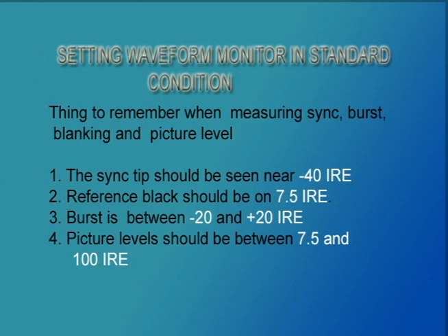The sync tip should be seen near -40 IRE. Reference black should be on 7.5 IRE. Burst is between -20 and +20 IRE. And picture level should be between 7.5 and 100 IRE.